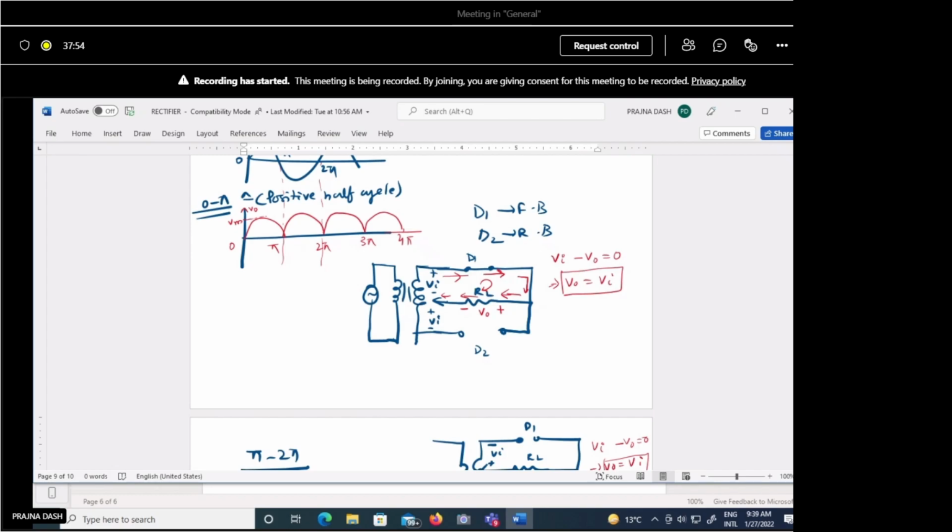Okay. So in the center tap full wave rectifier we are increasing the efficiency, but there are certain difficulties, like it is very difficult to find the exact center of the secondary winding. If you have seen a transformer physically, the windings have very small wires, and the number of turns is very high. So for that winding, it is difficult to find which one is the middle point or the center point of that winding.